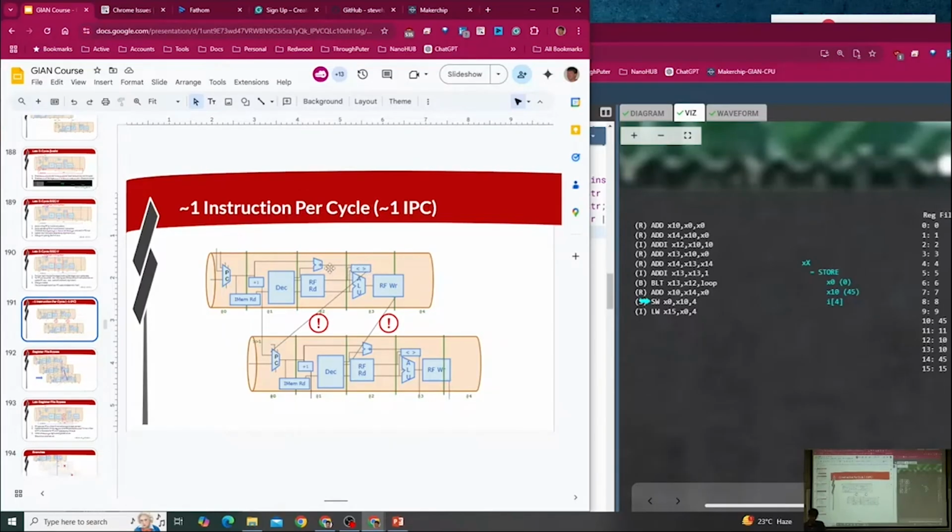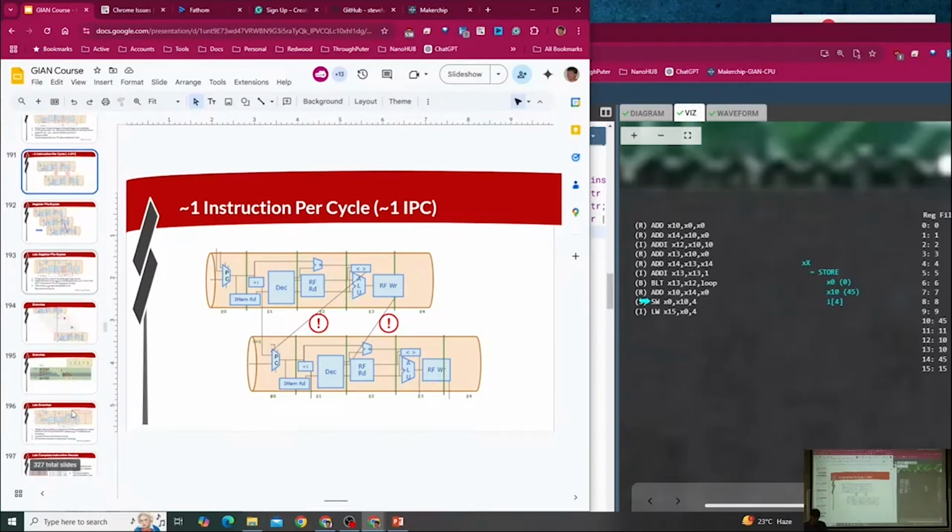So potentially, we could do this path a little earlier, right? We can do the offset calculation in the stage before. Potentially, we could drive that offset calculation to the PC mux. We already know whether we're a jump or not. We're not going to do that optimization. We'll just do it the same way that we did branches. If you'd like to try that optimization, feel free. Maybe I shouldn't say optimization. It's not a logic optimization. It's a performance optimization, right? But we'll treat it the same way with a 2-cycle delay to get the target.